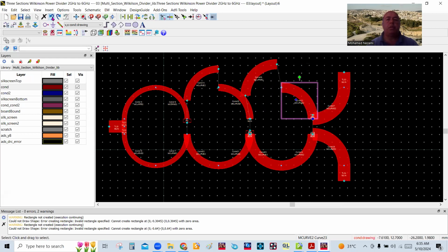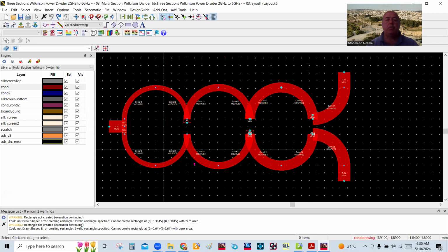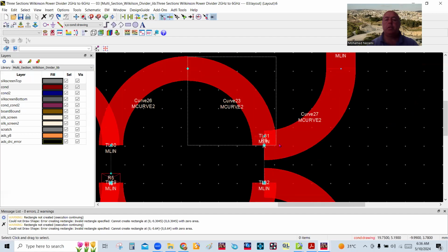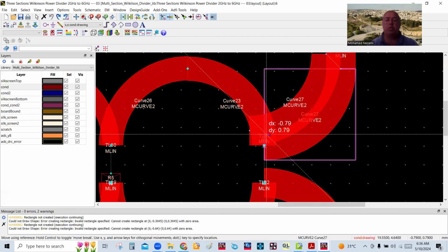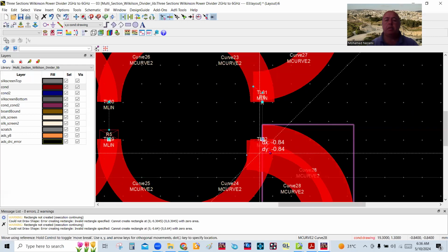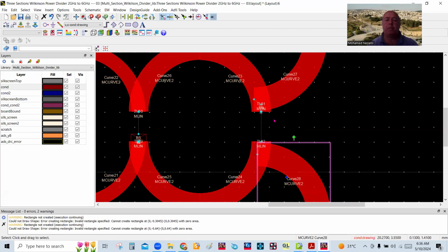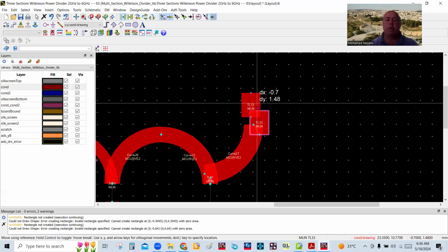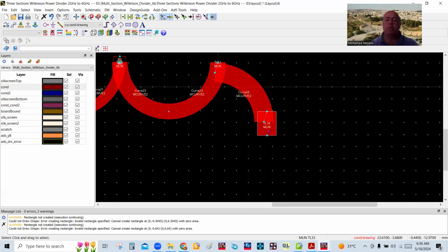And so the other thing you can visualize now is, look at this. You can start out with a higher impedance in here, a little bit lower impedance, a bit lower impedance, up to when you get to 50 ohm in here. Now you have to pay attention to this here so that the isolation is good. So you might want to move this here and still make sure that you have distance to solder the isolated resistors. So we can put this back here. This is the additional 50 ohm feed output feed lines, okay?